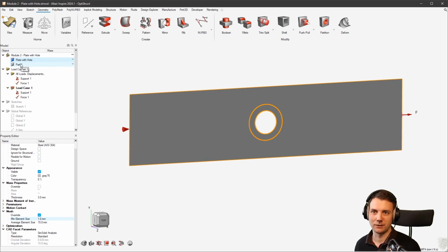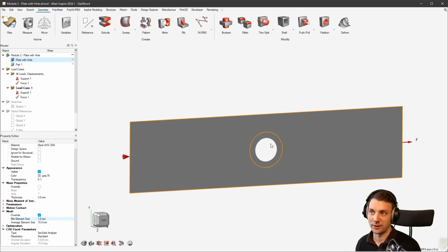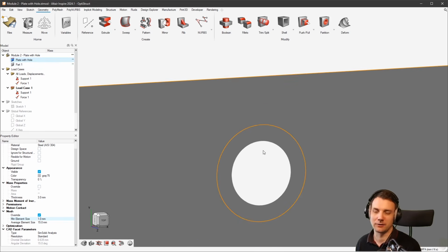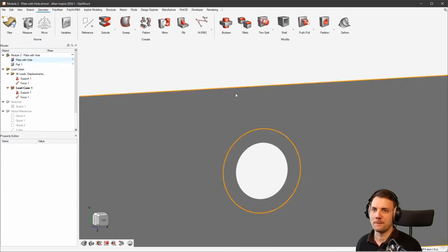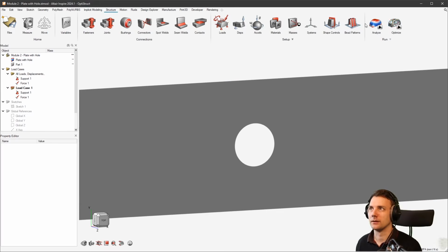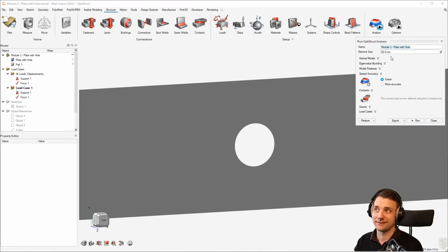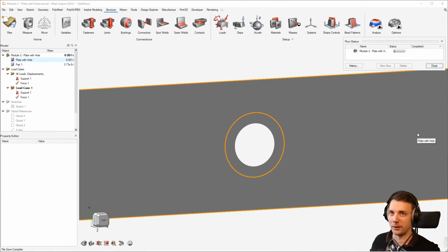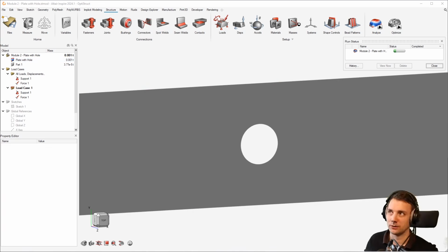The mesh will not look that good, to be honest, because we have to really make a shift between a coarse mesh to a finer mesh, and this will have its trade-off here. But as we just really want to take a look at this, I would say it's all right. Okay, let's go with it and run the analysis again. Again, it does not really matter what we put in here because we have put override to both of our parts, and thus we specified exactly how the mesh should look. Okay, again, I will hit the pause button and be right back.